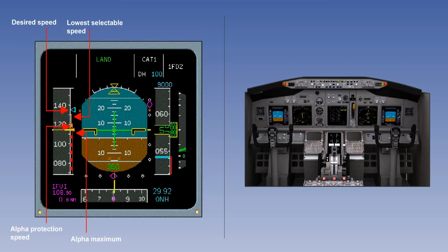Regulations stipulate that in large aeroplanes, the stall warning system must activate before the stall speed by an amount greater than either 5 knots or 5% of calibrated airspeed. It must continue to work until the angle of attack is reduced to at least the point where the stall warning was initiated.